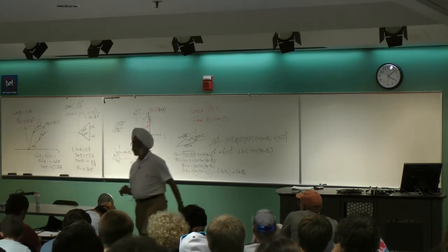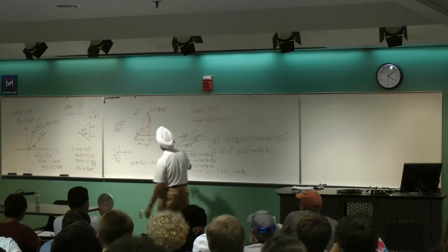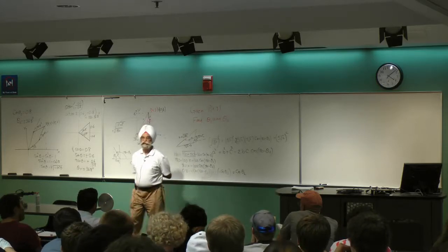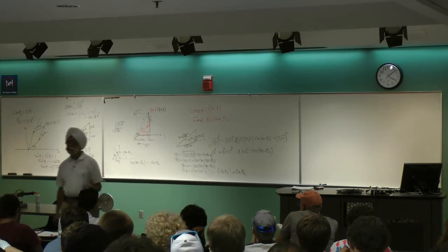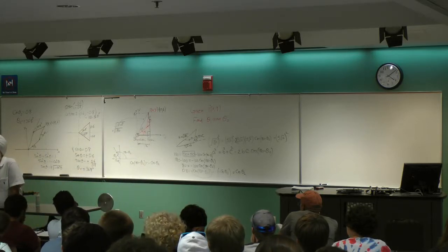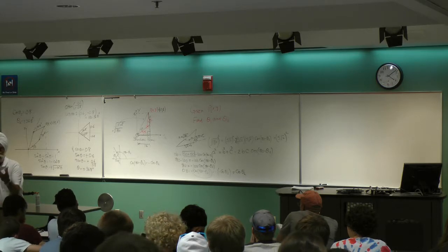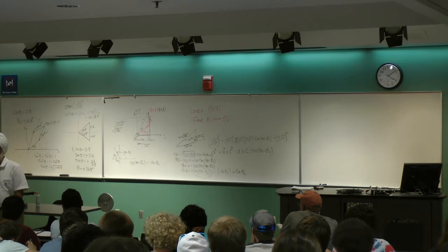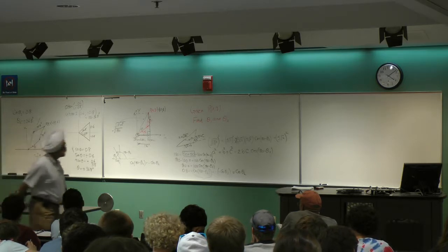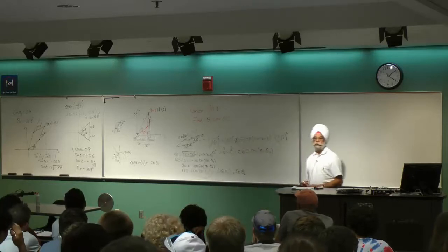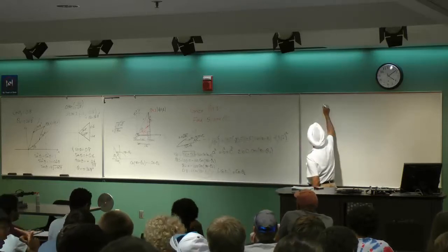So I know theta 2 is positive here. We know the angle theta 2, and we know it's elbow up. You need to know it's elbow up, and in this case it is, so 36.8 degrees. How do I find theta 1? Let's see if we can find the value of theta 1. All right, so let me redraw again.